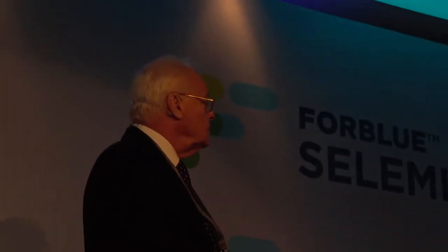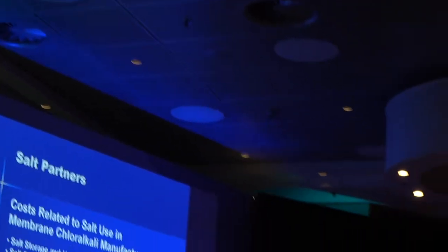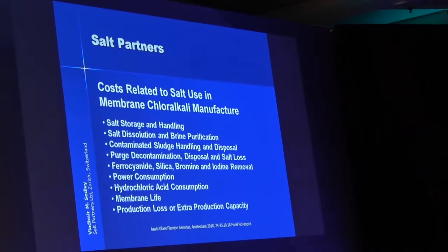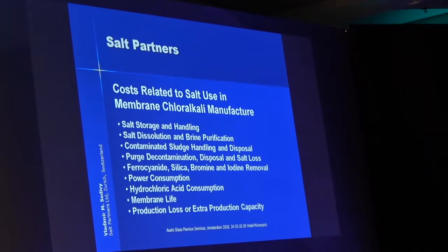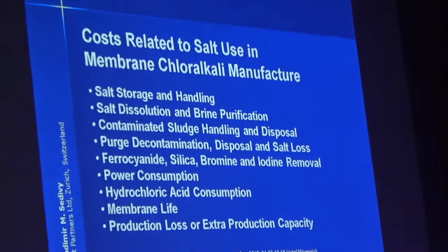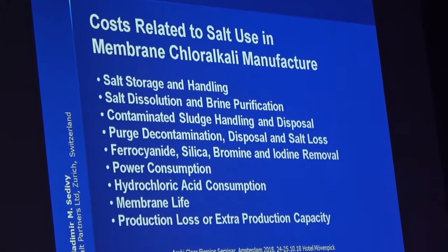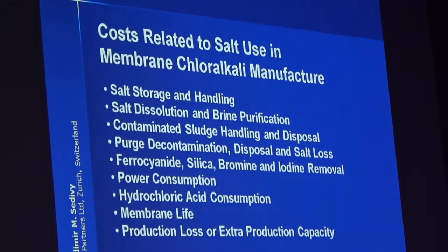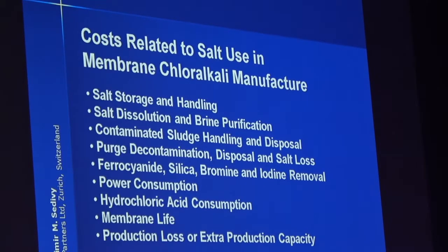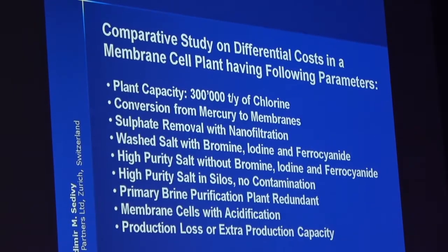Cost related to salt use in membrane chloralkali manufacture. That's what we have been talking about here. It's the salt storage and handling, salt dissolution, contaminated sludge disposal, purge concentration, ferrocyanide, silica, and so on. We have power consumption, hydrochloric acid consumption. We have membrane life and production loss of extra production capacity. That all is or can be due to impurities in salt.